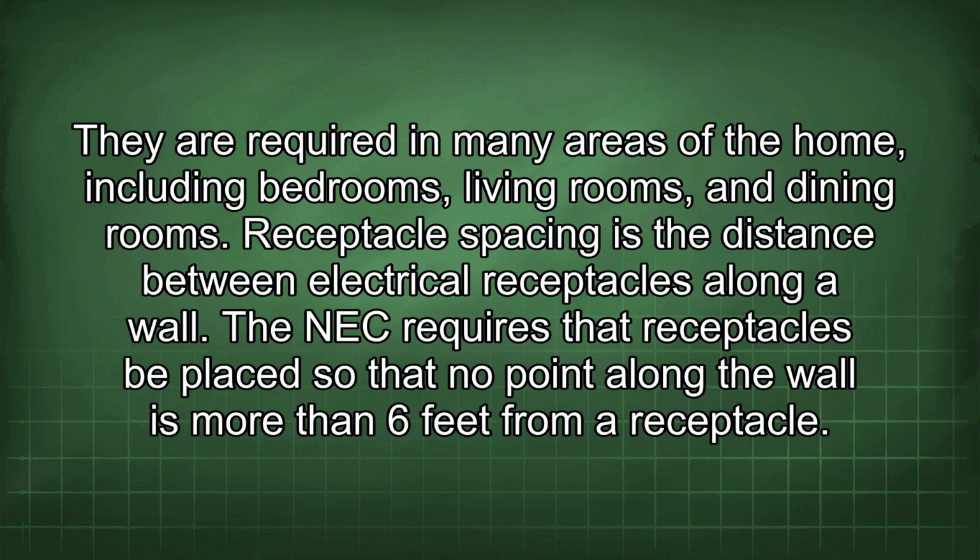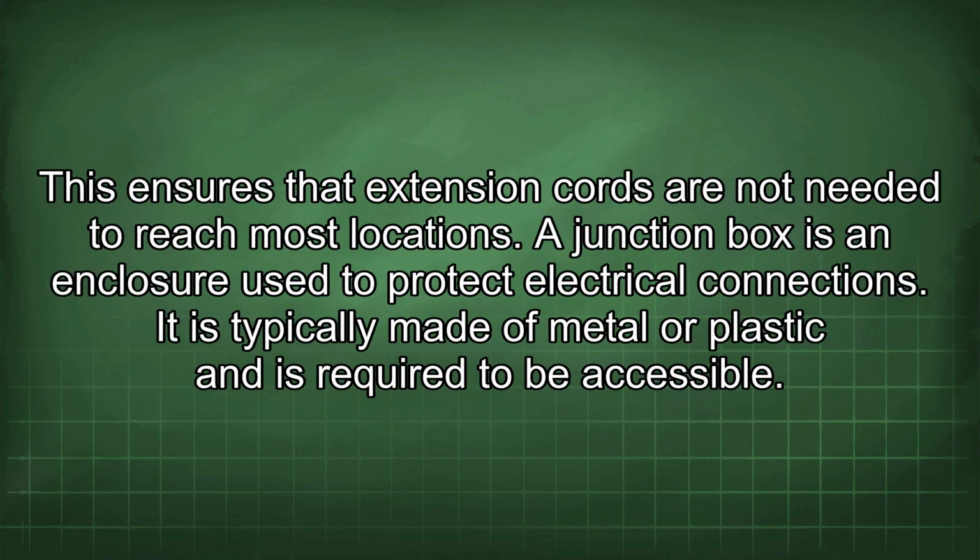Receptacle spacing is the distance between electrical receptacles along a wall. The NEC requires that receptacles be placed so that no point along the wall is more than 6 feet from a receptacle. This ensures that extension cords are not needed to reach most locations.